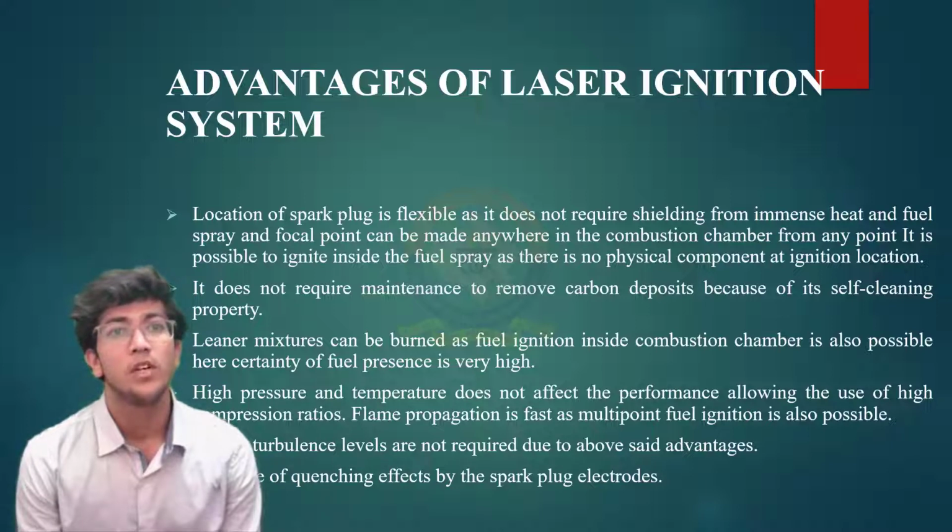Lean mixtures can be burned as fuel. Ignition inside the combustion chamber is also possible here, where certainty of fuel presence is very high. High pressure and temperature do not affect the performance, allowing the use of high compression ratios. Flame propagation is fast as multi-point fuel ignition is also possible. Higher turbulence levels are not required due to the above said advantages. Absence of quenching effect by spark plug electrodes.